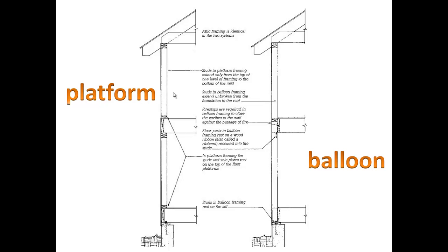the other method that's more common today is what we call platform framing. And platform framing basically starts at the foundation, sill plate, they build the floor structure, gives them a working platform to work on. They can build the first floor walls, construct the second floor platform on top of that, then construct the second floor walls, and then construct the roof on top of that. The advantage being that the framing becomes much easier to handle by one person. One person can build a home all by themselves for the most part, maybe with the help of some chain falls and some lifts, but